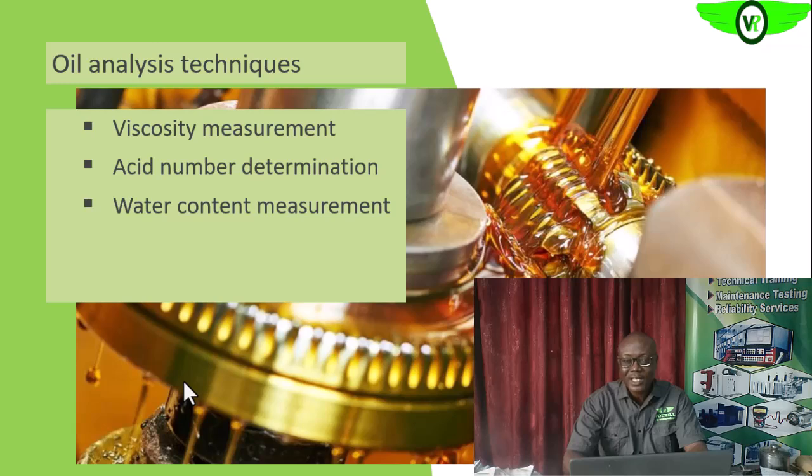Are we getting it? And that will eventually increase the wear and tear, which will further increase the contamination of the lube oil, because those oxides of metal that will eventually form will flake out and contaminate the lube oil further.